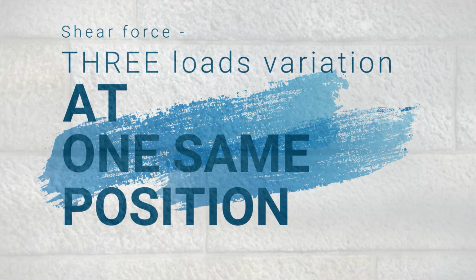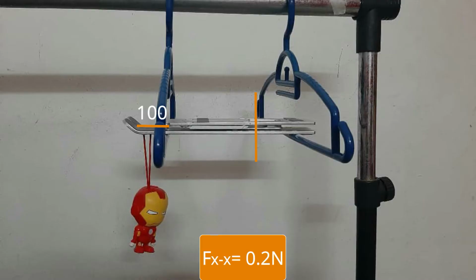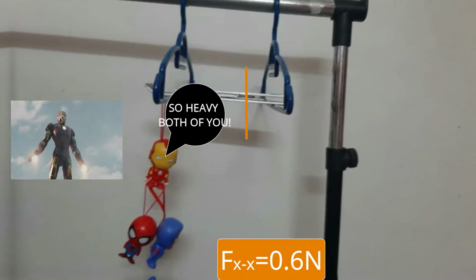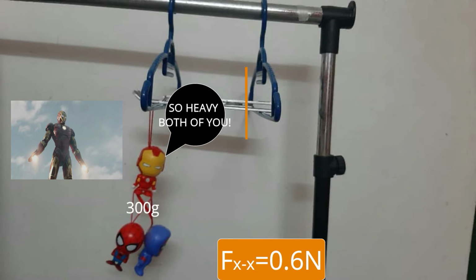The first objective is to determine the shear force at cut section from only one position, which is at P1. Initially, 100 gram is placed at 100 mm left from B and 0.2 Newton is observed. Next, repeat the experiment with 200 gram and 300 gram at the same position and observe the shear force. 0.4 Newton and 0.6 Newton are recorded at the display respectively.